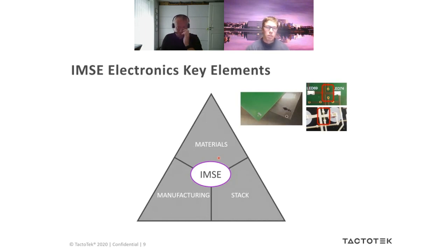On the material side, the main difference is the substrate of the electronics. We don't have FR4, but instead we have thin plastic film. In IMSC, traces are not solid copper, but instead we are using silver ink, which we print by screen printing. If we need multi-layer layouts, we need to design dielectric on crossovers. So those are the main differences on the material side. Materials are different, and this means that their electrical characteristics are different as well.